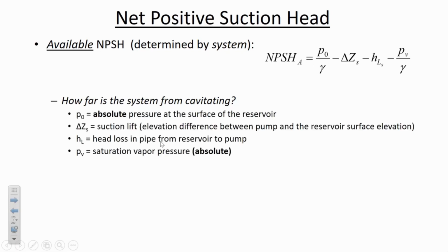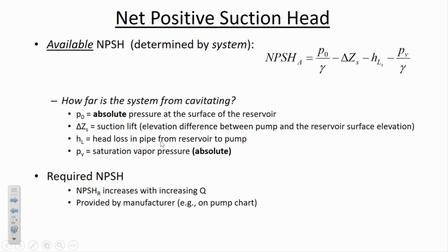So here are the terms of the NPSH formula, and the required NPSH increases with increasing flow rate. It's a physical characteristic of each pump, being a little bit different, and the manufacturer will tell you at a certain flow rate how much net positive suction head is needed.